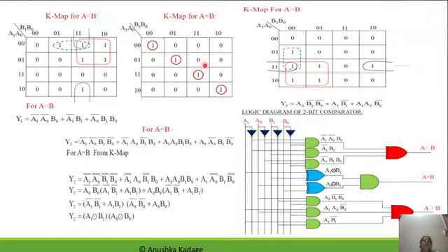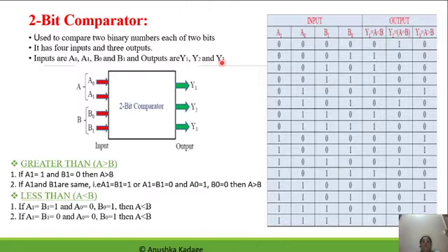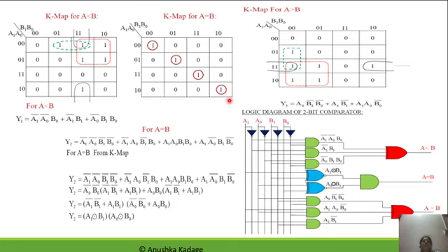Next, for the last four elements, we first write 0001, so it will be mapped as 0001, and finally 0010. But we can see that the ones are present at diagonal places. That means we cannot group more ones, and we can write each of those terms as it is.